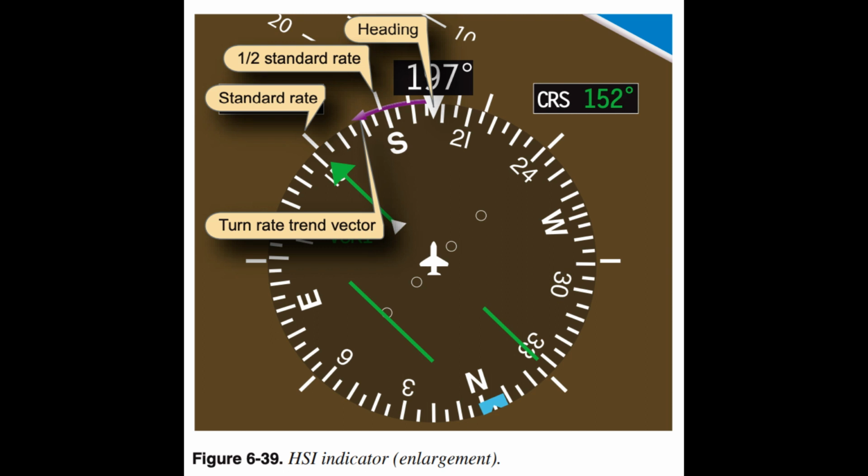Common errors. Fixation. Fixation, or staring at one instrument, is a common error observed in pilots first learning to utilize trend indicators. The pilot may initially fixate on the trend indicator and make adjustments with reference to that alone. Trend indicators are not the only tools to aid the pilot in maintaining the desired power or attitude. They should be used in conjunction with the primary and supporting instruments in order to better manage the flight.